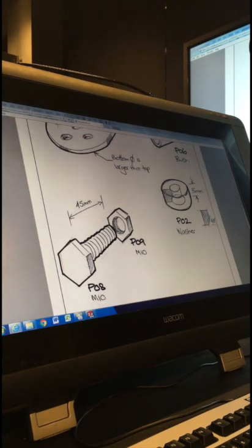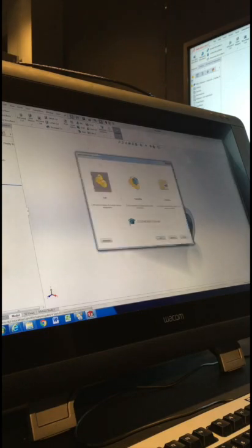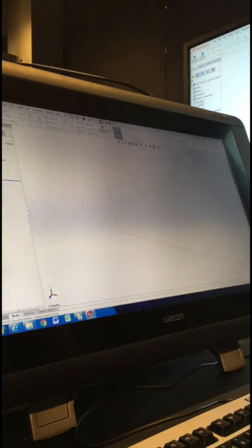We can tell it's a revolve because it's a 360-degree rotation. It's the same shape, where there's a section sliced through, and that section is this little hatched area we can see. If we sketch that section, we can revolve that whole shape in one hit. So what we're going to do, again, new part, and on the front plane, new sketch.